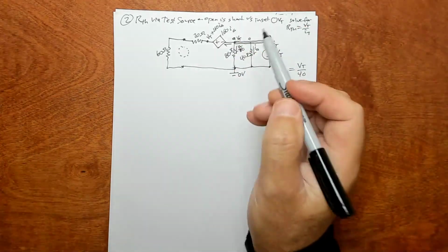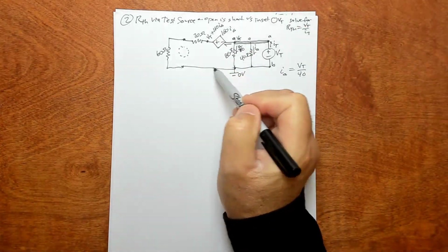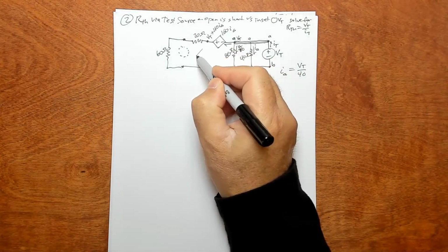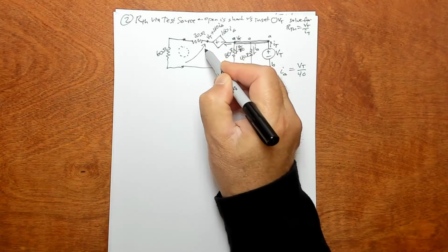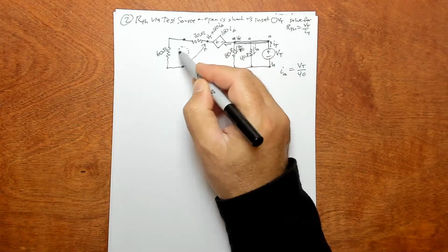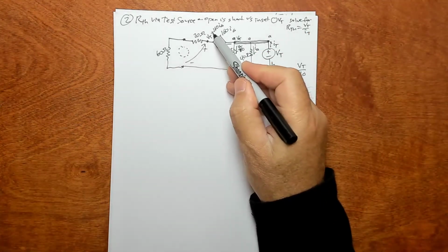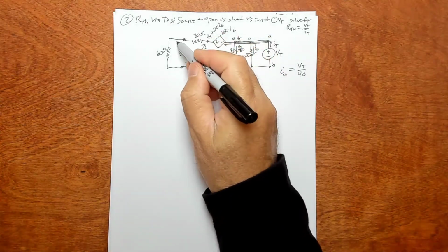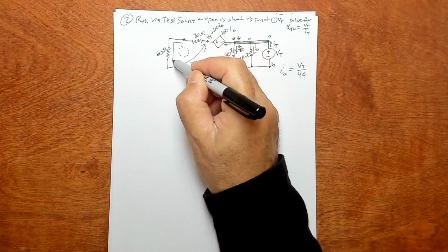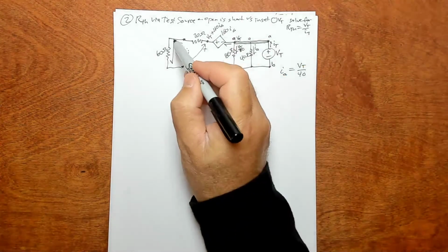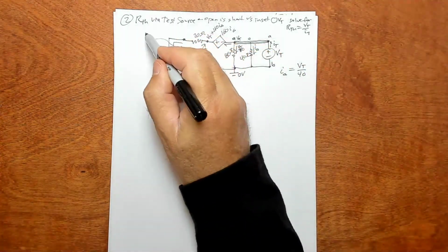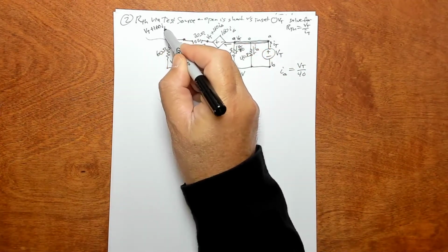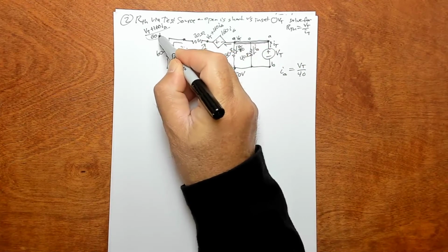So the voltage at this terminal is VT plus 160 I delta, and then we're back to 0 volts. So basically, across these two guys is the potential difference, VT plus 160 I delta. So that'll give you the current through this branch here. It's going to be VT plus 160 I delta over 60 plus 20.